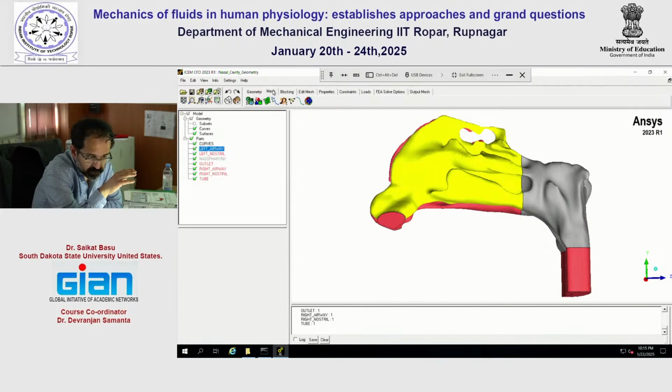To do that, we will do a second layer of grid resolution where we develop prismatic cells along the walls. But that is the second phase of meshing. Let's first try to get the tetrahedral mesh built. So we go to mesh, we go to this first option under